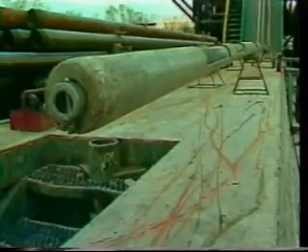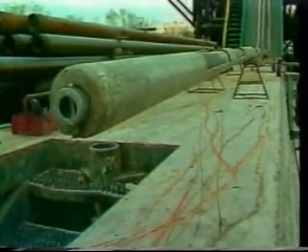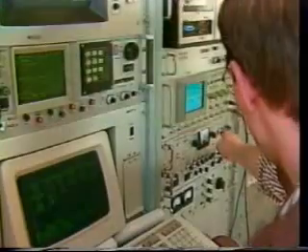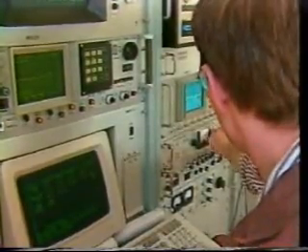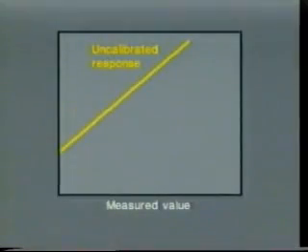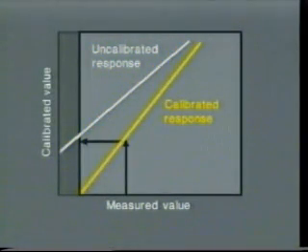For example, the induction tool shown here was shop calibrated by several tests. Based on tool measurements obtained from these tests, the uncalibrated induction responses of this specific tool were then mathematically adjusted to produce standard readings. All test results and calibrations are included in the shop summary shown here and are made part of the permanent record of the induction tool.